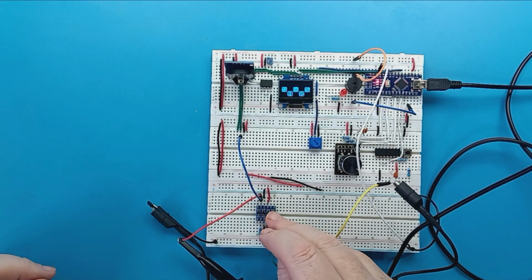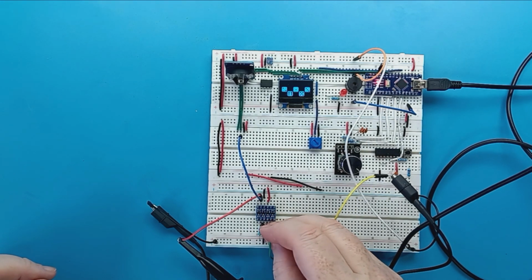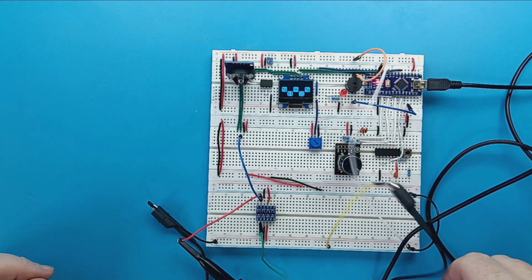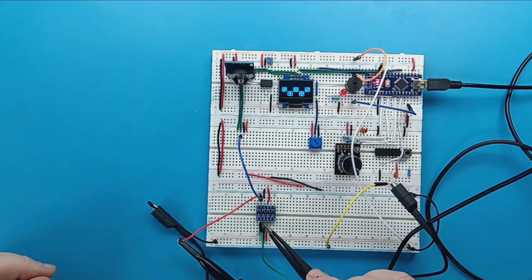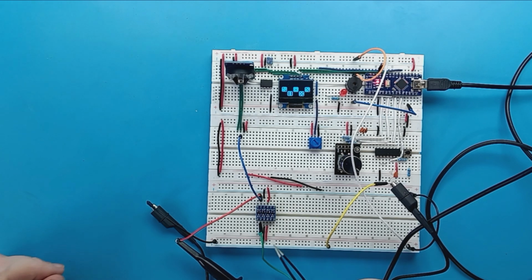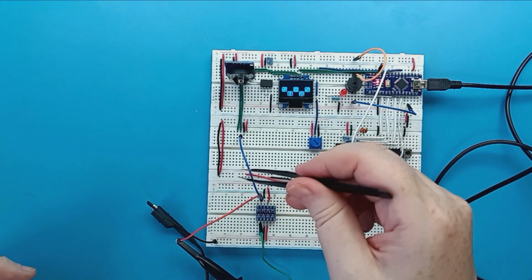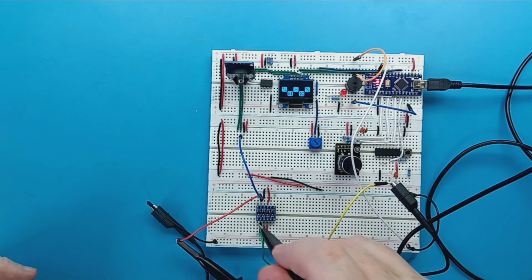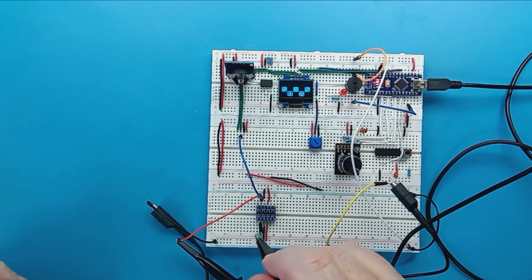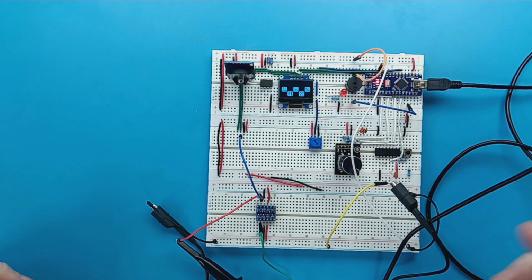And then on the 5 volt side, I'm going to hook up channel 2. So I've got my channel 2 signal I'm taking from HV3, and I'm using LV3 on the other side. So LV3 through the logic level converter to HV3. So we have everything hooked up.